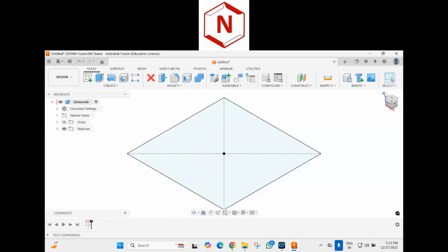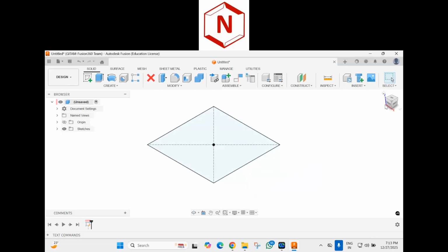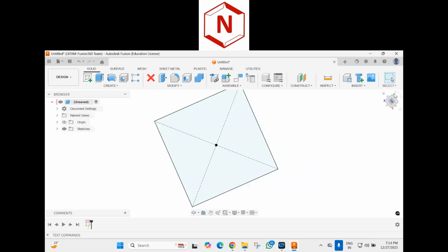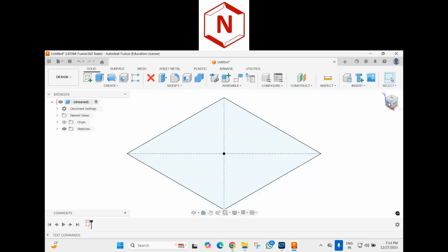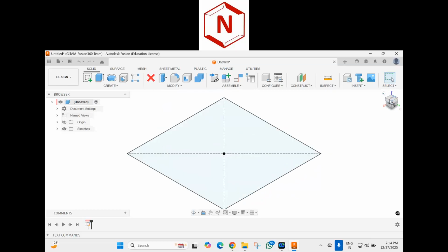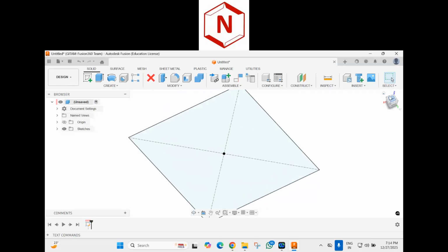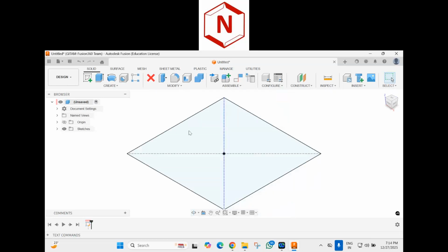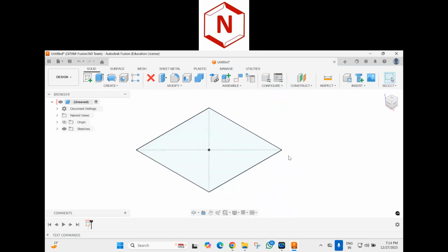If you click on home, it is going to take you to the home view, and you can activate various views like top view, front view, as well as the right hand side view. Whatever view you want, you can select like this. If I click on the small home option here, which is showing in blue color, it is going to take me to the home view, which is the isometric view.